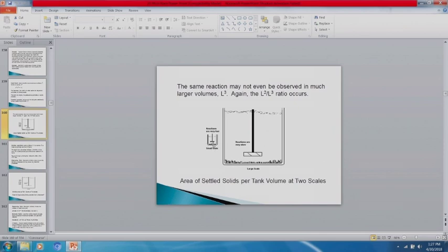They were available over here in the fact that there wasn't a lot of concentration, surface concentration needed. So the small scale of the reaction worked well, and in the large scale the reaction essentially disappeared because the solids were on the tank bottom. Essentially, you need to raise the solids off the tank bottom and have them fully exposed to processing, and then you have a working system.